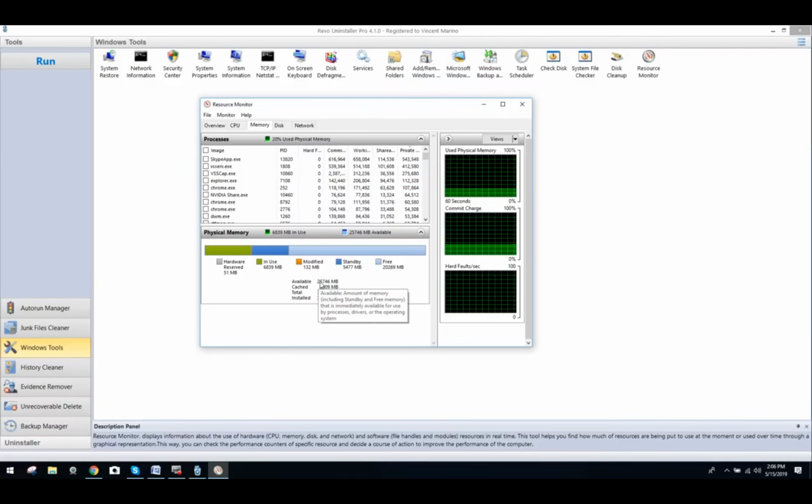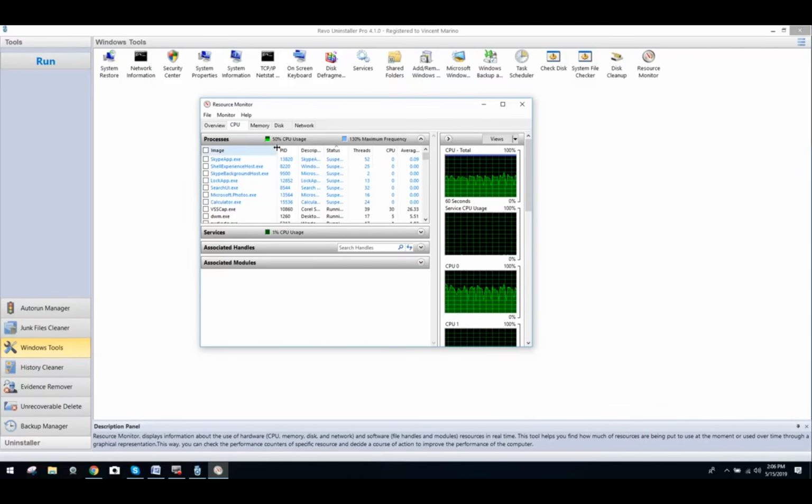If you notice that this available memory is ridiculously low, let's say for instance you have 8 gigs of memory installed and you're only showing 3 gigs available, I would highly recommend bumping to 12 to 16 gigs. Matter of fact, I don't recommend using any computer with less than 12 to 16 gigs for this reason, especially with these modern operating systems, because CAD/CAM software is a memory-hungry application, a lot of math being done. So pay attention to this. This is the heart of your system. This is your memory.